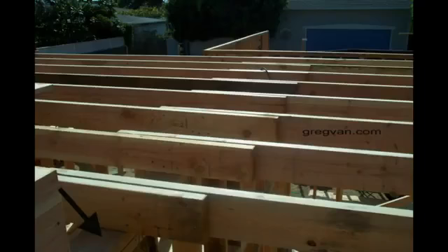However, if you run across something like this, where the ceiling joists lap over a wall, you can see that the end of the ceiling joist on the right and the end of the ceiling joist on the left are actually sitting on top of this wall. There would be a good chance that this would be considered a structural load-bearing wall and would not be able to be removed without some type of structural engineering and redesigning of the structure.